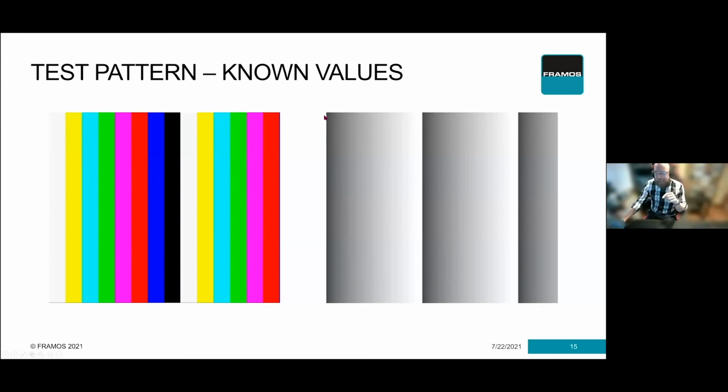What this means is I can tell you for every line what the value should be for a particular pixel. And so, using the data sheet, I know which pixel should be on which data connection, and therefore I can see if there's an issue with a particular data connection. Potentially swapped polarity is a very big one that we see, or maybe one is just not giving any data. It's giving either an error, but more typically it's just giving all black, all zeros or all ones. What we would then see is a vertical stripe pattern on top of this. So when we know what we should see, we can tell if we're looking at it in the correct way.